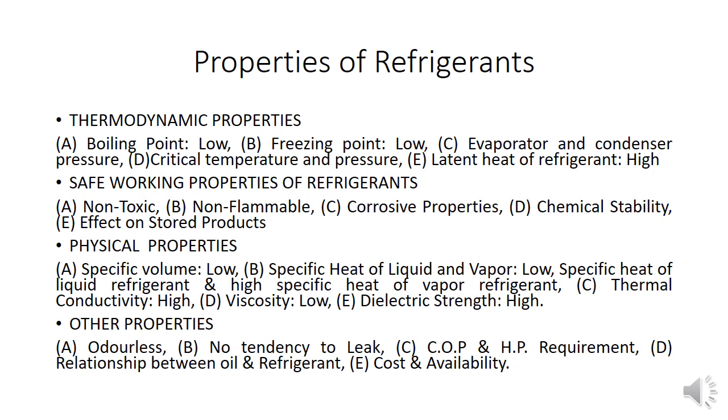It should be odorless, and it should not be miscible with oil. So whenever oil comes in contact with the refrigerant, it should not be miscible. And then availability and cost. Availability is the most important factor, as for large industrial plants there shall always be a possibility of requirement of additional refrigerant. It should be available easily.